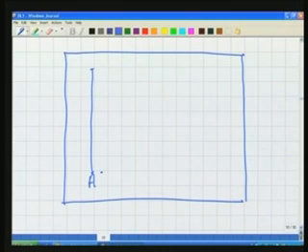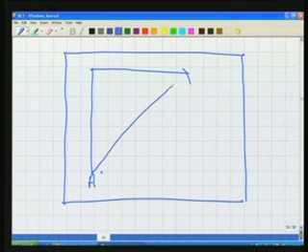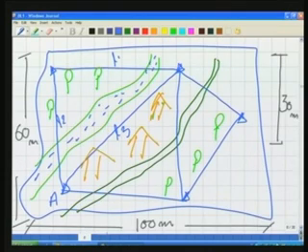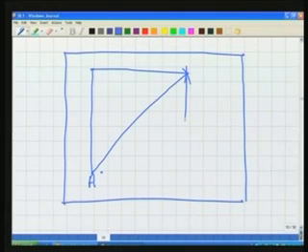We can measure the angle also, I am not talking about the angle now, and from here we can take the arcs of the rest of the 2 lengths. So, this point is fixed. Similarly, as per the triangulation figure there, we will draw the rest of the triangulation figure.